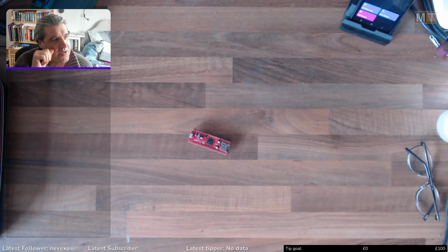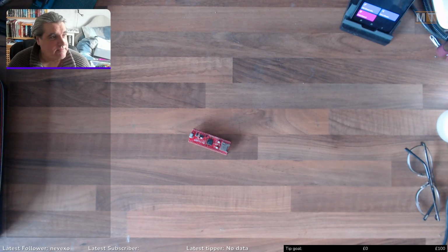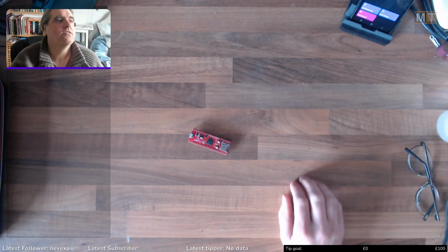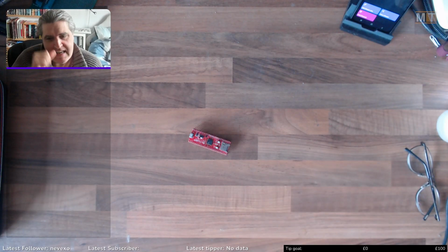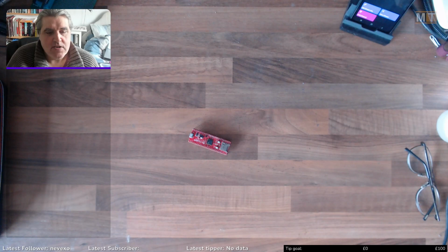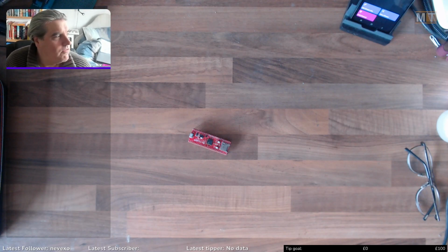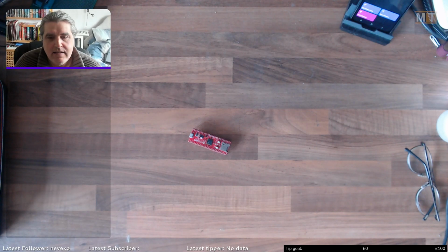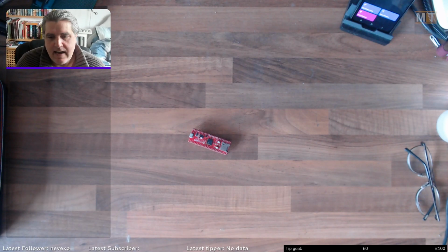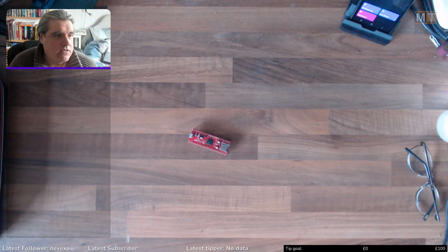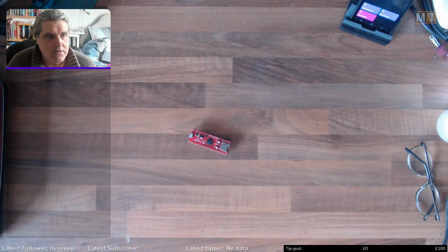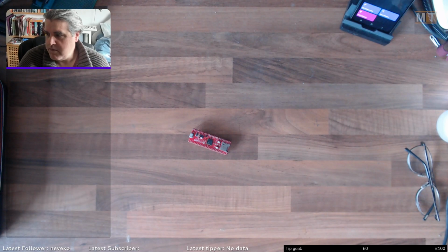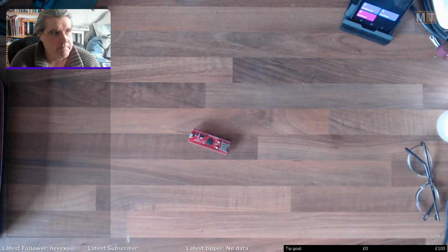Okay, what am I doing today? Well, I have a number of projects where I receive logic analyzer traces of data dumps from displays, and I have to take those traces and decode them and create emulator systems to interpret the data, re-render it out and output it to a different display.